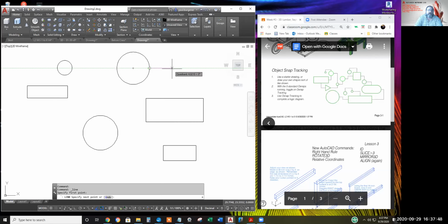Okay, now where do I click again to begin the downward line? I need to acquire the point at the midpoint on this rectangle. And tell us when you click. Right there, I left click. Okay, now you're going to click at the bottom and the midpoint. Correct, using the midpoint object snap. Now I get it. Thank you. Similar again, quadrant, acquire, click.